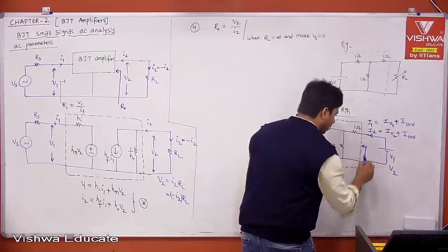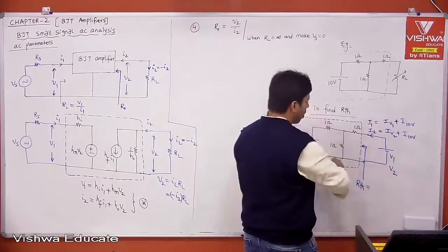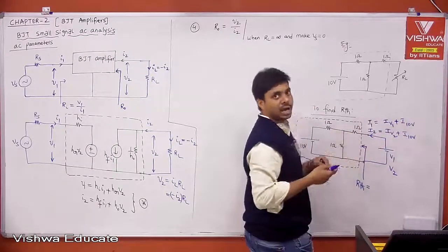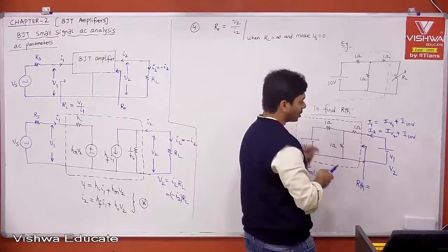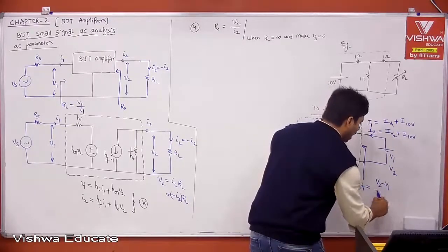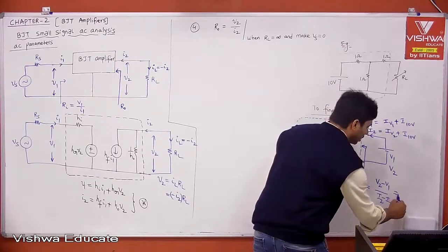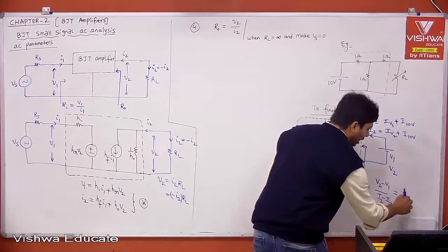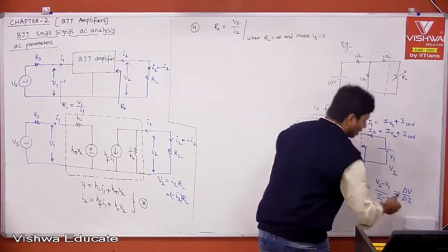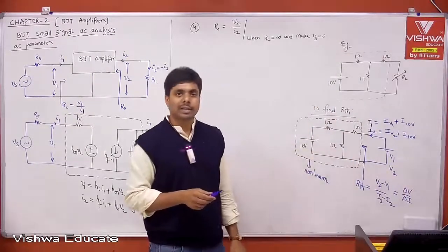Now I am defining R Thevenin. You know what R Thevenin is? This is a black box, but you know voltage source, regulator, power supply, ammeter and all. We are trying to find R Thevenin. If you don't know the black box, then what is R Thevenin? V2 minus V1 divided by I2 minus I1. This is nothing but your dynamic definition, which I told you, right? Because this is nothing but delta V divided by delta I. That is your dynamic definition, which I already told. Because the network is non-linear, we have to go ahead with the dynamic definition.